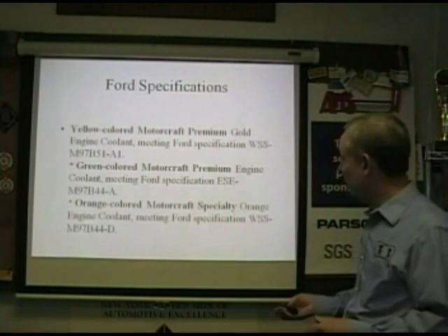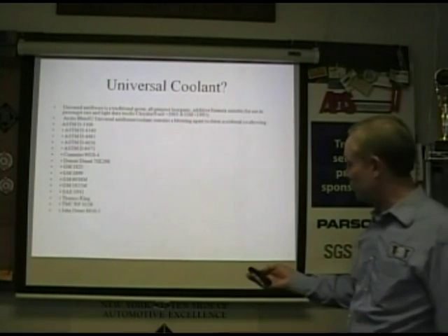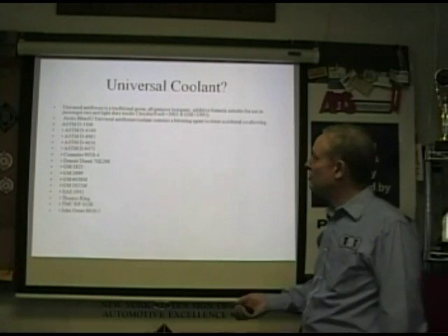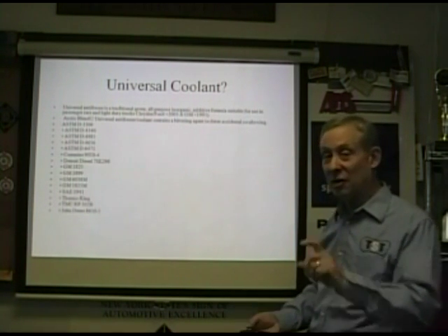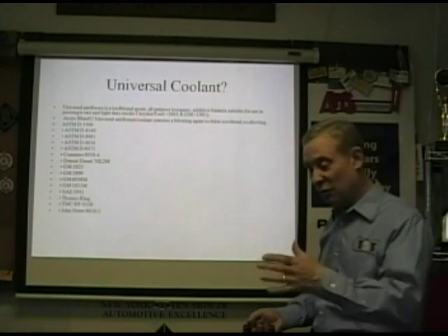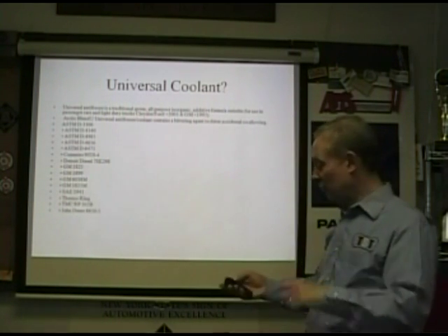Yeah. No. You have to read the specs. Again, just make sure it's for the vehicle you're working on. These are all a bunch of specs. Again, you don't have to memorize this stuff. What you have to do is look it up on a chart and make sure that the coolant, that jug, or that drum, meets the spec for what you've got in your bay.